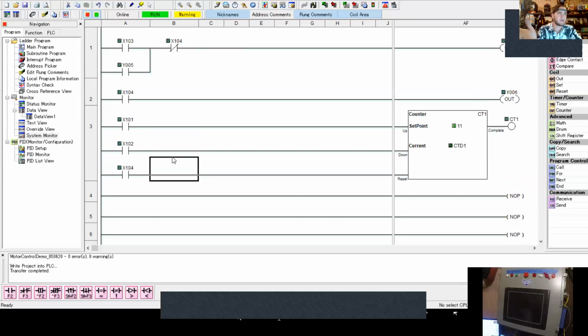So why would I set that up to have the E-stop reset the counter? It sets the speed to 0. Exactly. So if I have an emergency stop button, I want to make sure that it kills everything, and that's a really good way. We already have it set up to tell the VFD to stop, right? But this is an extra layer of security where I reset my VFD output to 0 also.